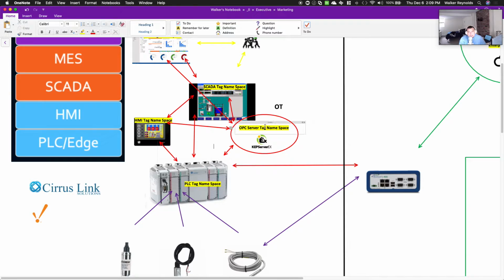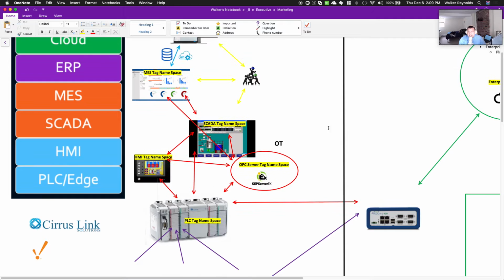Now, Kepware is a little different because you can do what's known as an explicit OPC UA read. That means I could have an OPC client out here that sends a command to Kepware, gets down to the device level in the name tree, okay? And it says, go to that device and ask for the register that is at MW1, okay? So that's memory word 1 inside of a Siemens PLC. I wouldn't need to have a specific tag inside of Kepware to do that. So I could do an explicit read. But in most cases, people are building tags inside of Kepware.